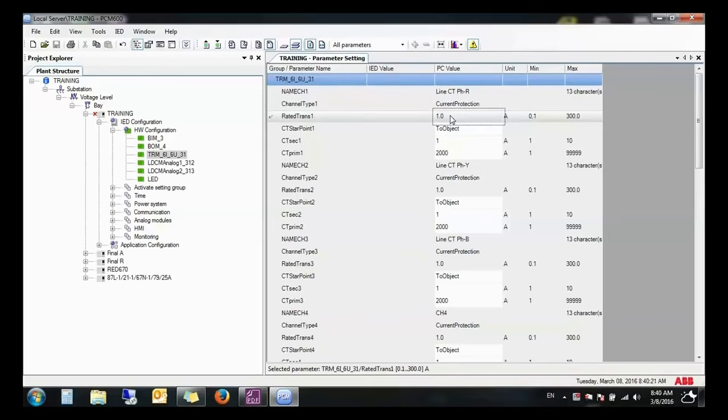It's all wrong, all right? Which means approximately 1 over 5 in it. And at the same time, if your CT is 2000 over 5, it will be wrong, because that means there is a large current flowing continuously in the CT, which is rated for or can handle up to 1 ampere. Maybe it can handle 3 amperes continuously, but not 5 amperes continuously.